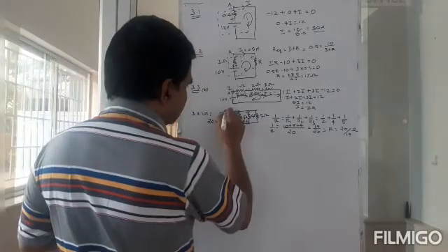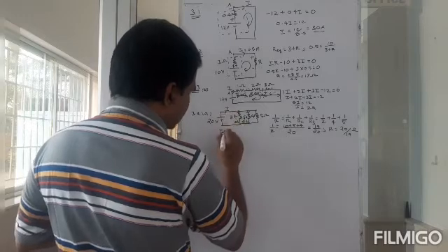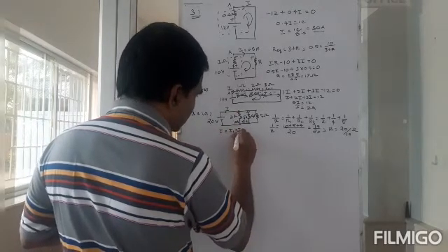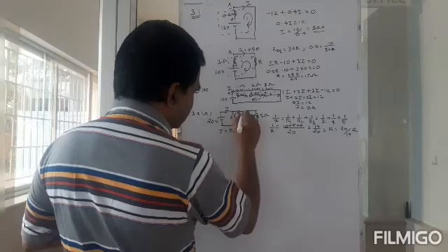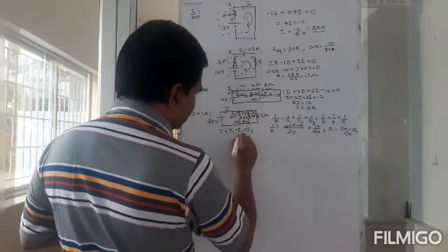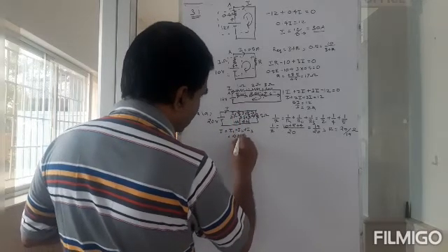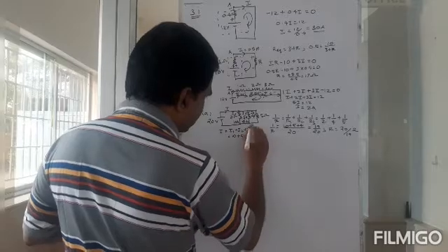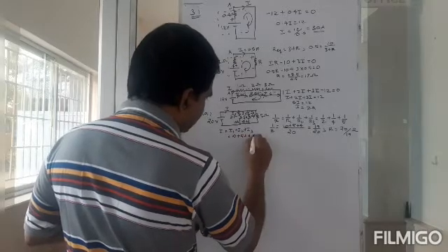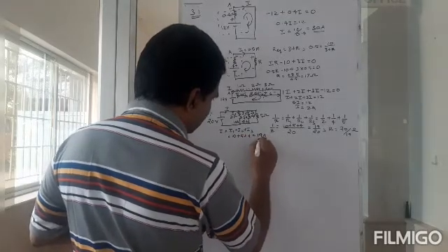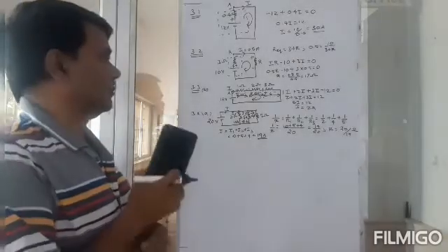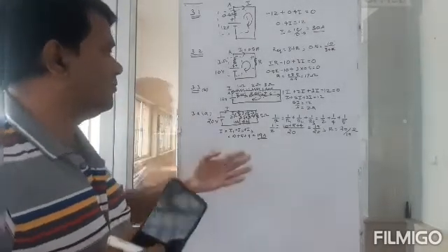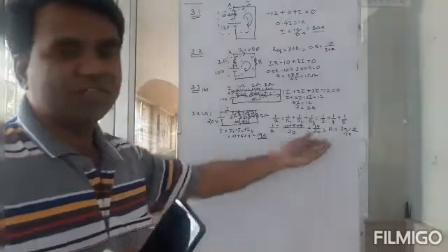Okay, 10 amps here, 5 amps here, and then 4 amps there. So totally this I is equal to I1 plus I2 plus I3. This is I1, this is I2, this is I3. I1 is 10, I2 is 5, and I3 is 4, so it's going to be 19 amps. Okay, so that will be the total thing. And that can be found using the effective resistance also, right?